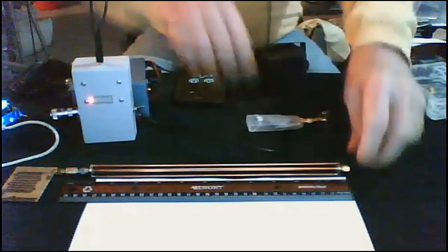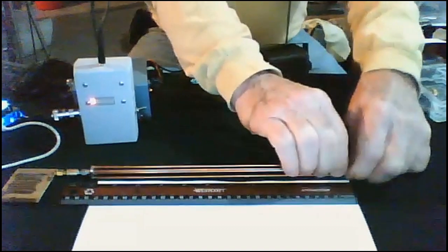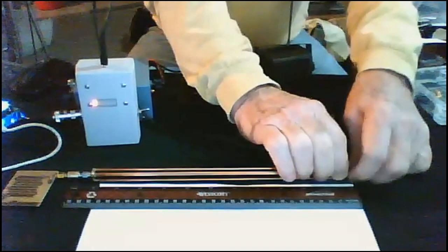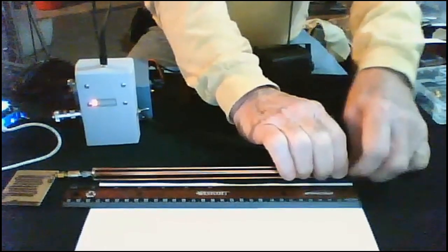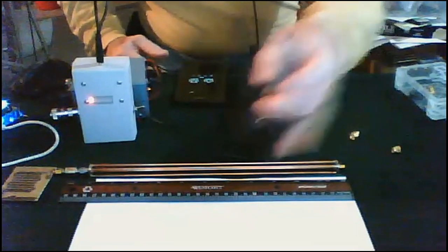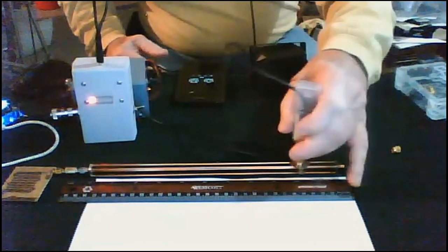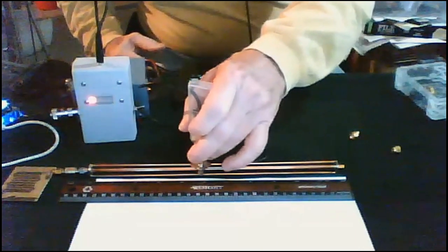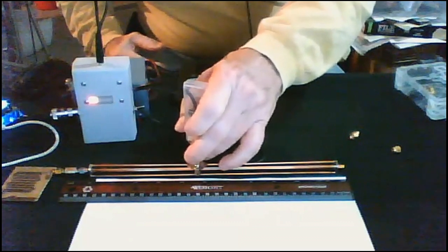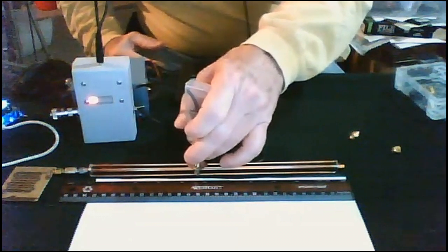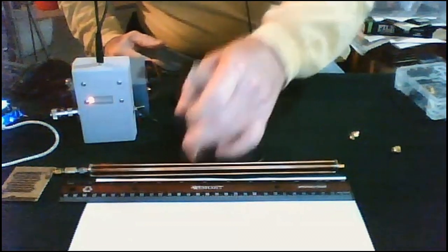So that's with a short circuit on the end. Now I'm going to make an open circuit by taking the short off. Now, remember the 0 was roughly there. Now it's here and here. If you're paying attention, we've moved the nulls a quarter wave, but we haven't changed the distance between them.